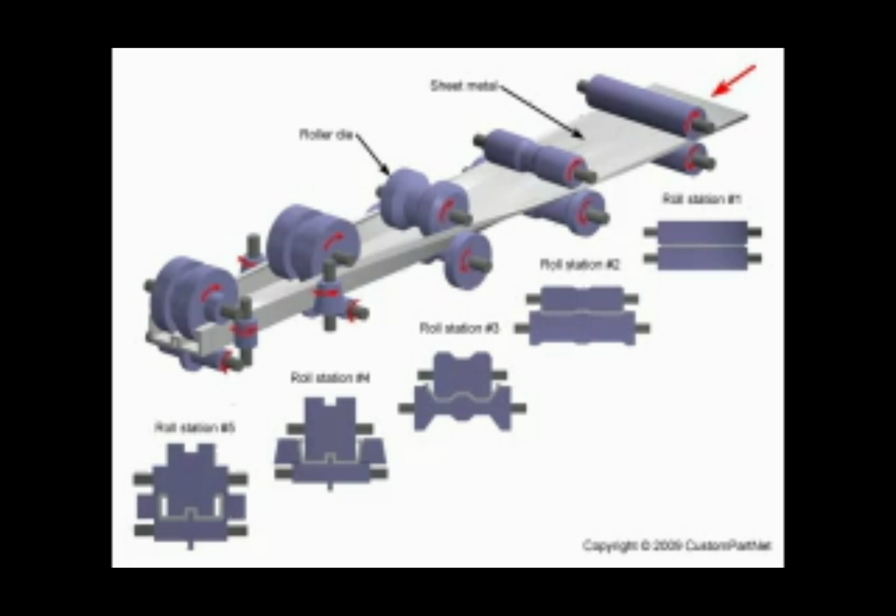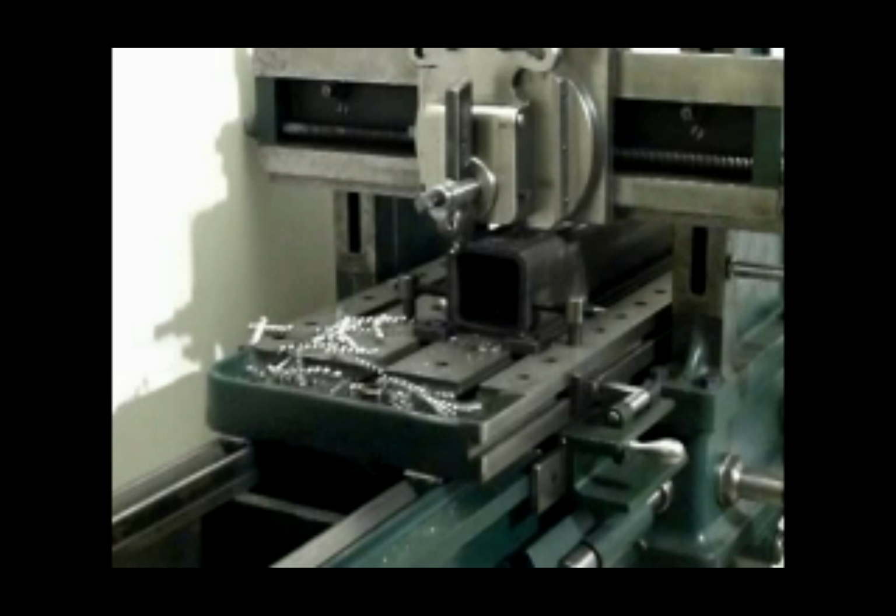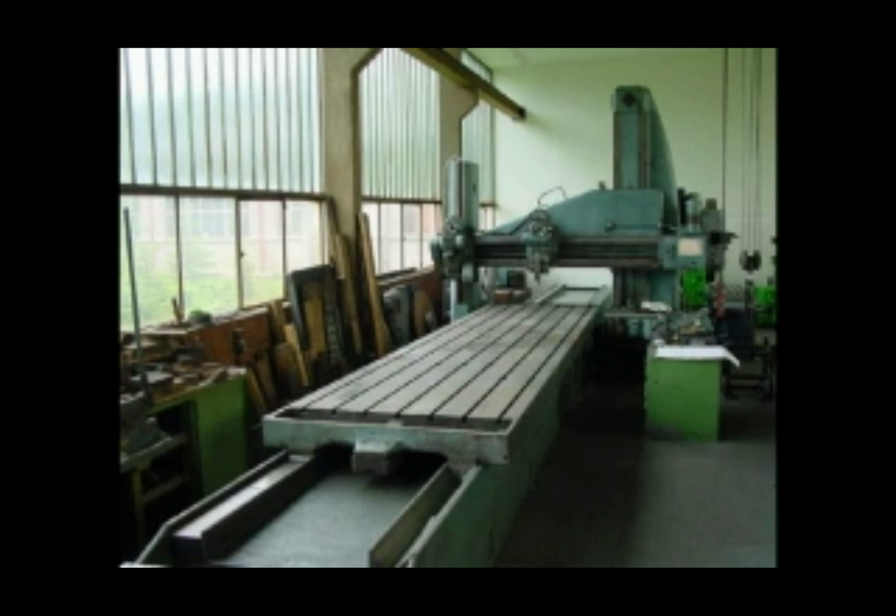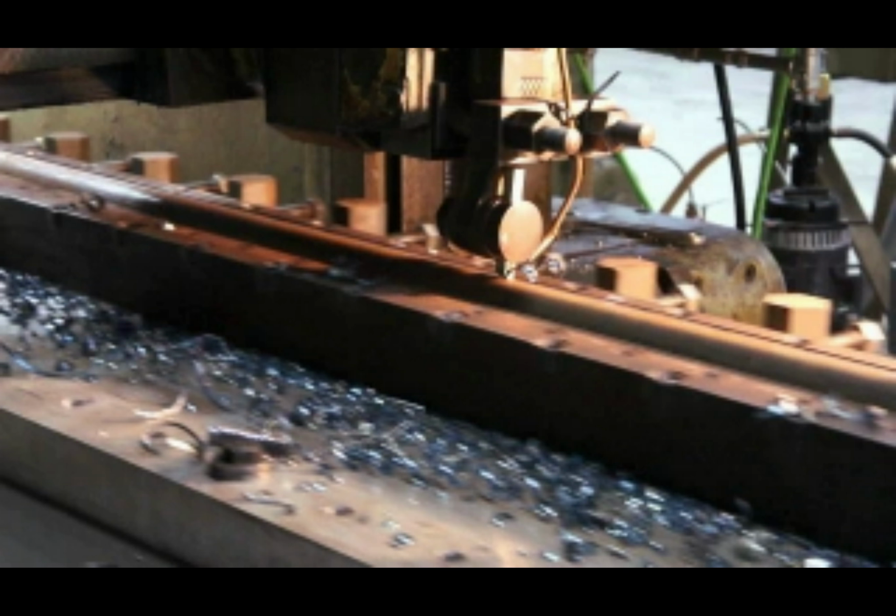Shaping or planing is a material removal process in which the workpiece reciprocates against a stationary cutting tool, producing a plane or sculpted surface like a groove. In shaping, the tool is brought into position with the workpiece and then repeatedly moves in a straight line while the workpiece is incrementally fed into the line of motion of the tool. This then produces a flat, smooth, and sculpted surface.